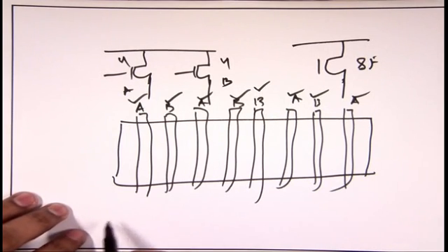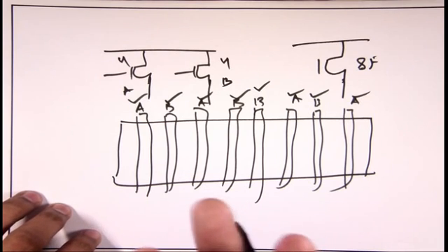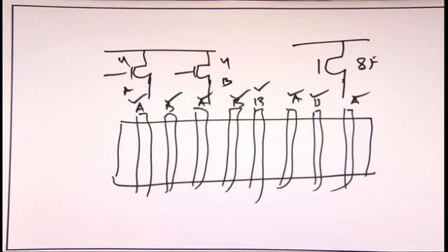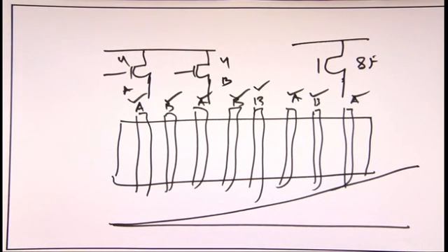See, the process variance: silicon is an anisotropic material, meaning it is not uniform everywhere, the doping profile is not uniform, so it may vary in this way. Just to give you a bird's eye view of how important this process variation is: two years back, I designed something on a 6-inch wafer in a process foundry, and I asked them to give me the sheet resistance profile of that wafer. And I found there is 10 to 12% variation in the sheet resistance throughout the 6-inch wafer.